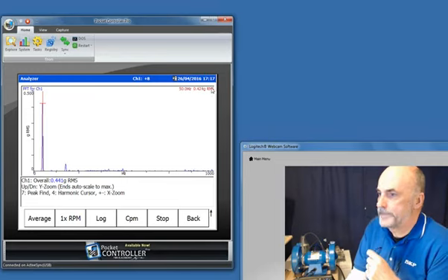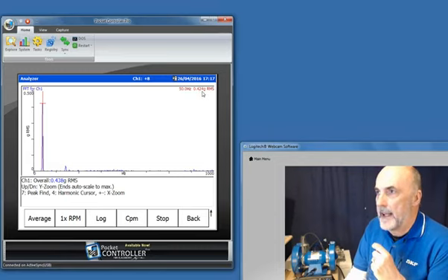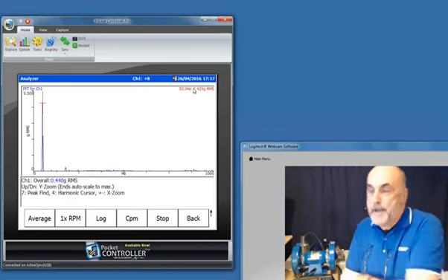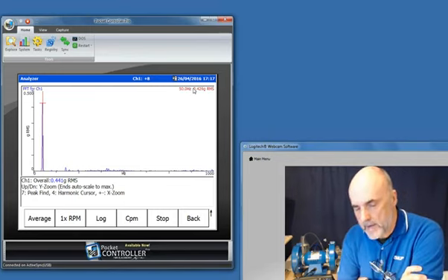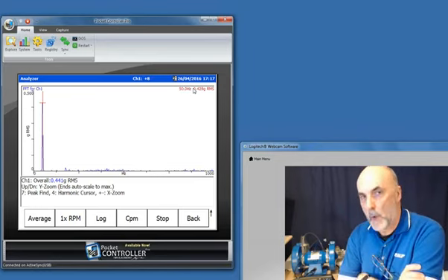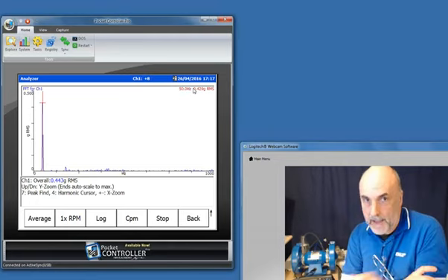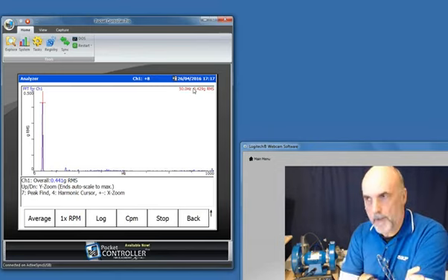But the thing to note, look at the value there, 0.4 G RMS, and that value isn't varying an awful lot. It's rock steady, and that is a classic example of rotor unbalance. If you saw a signal that was that steady, that stationary, that deterministic, there really wouldn't be much point in averaging. You might take 2 or 3 averages just so you can tick the box that you've averaged, but there's very little point. One measurement would be perfectly adequate.